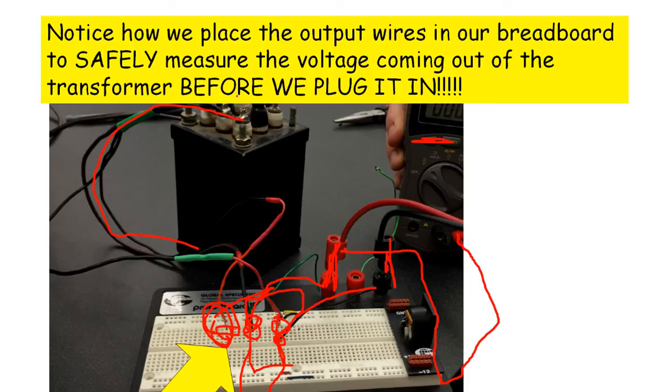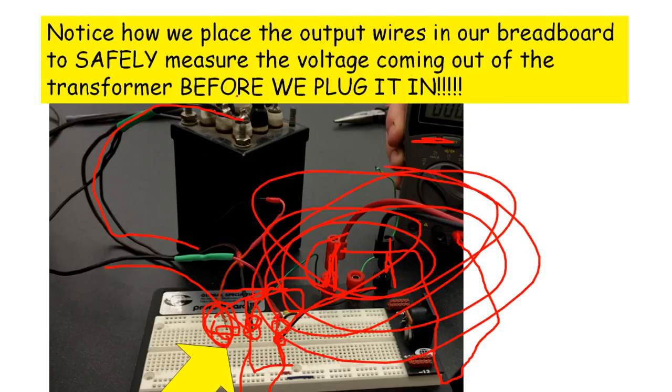Then you'll leave this in there, unplug it, and take the leads of your oscilloscope instead of the voltmeter here. We'll have the oscilloscope hooked up, and you'll look at what the waveform generated by our power company looks like and see how close it is to a perfect sine wave.